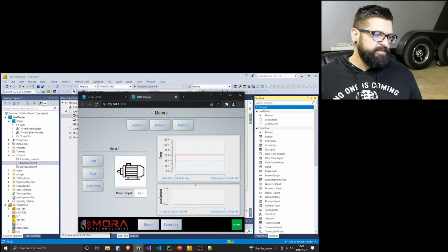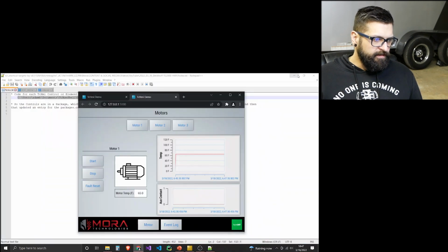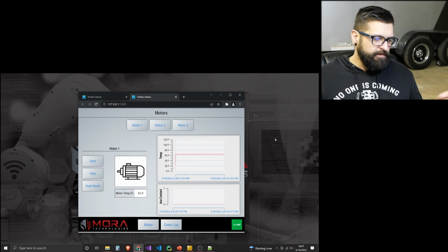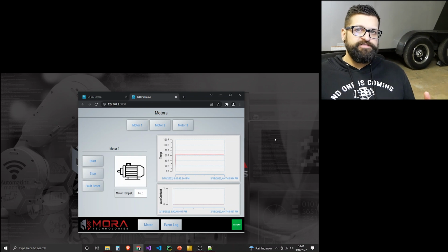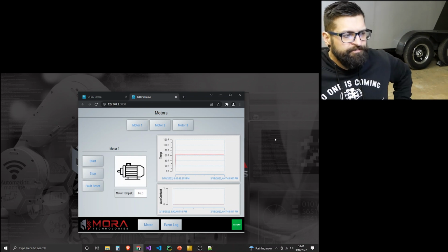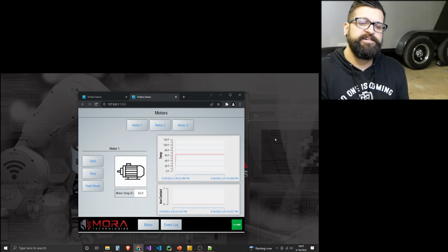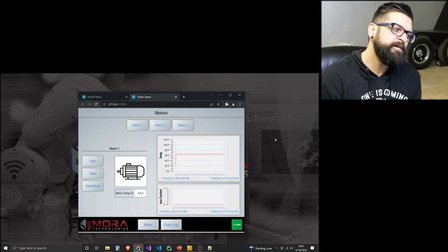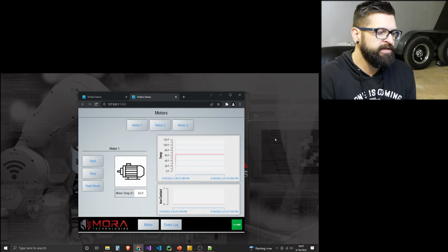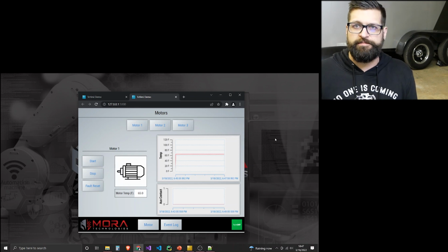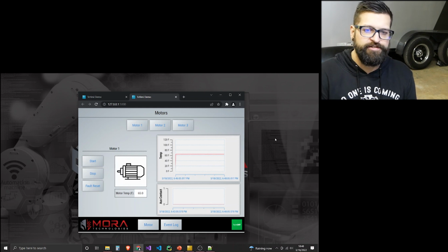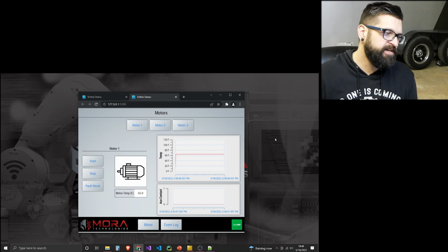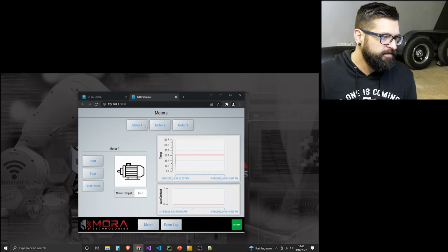What that came together with is this HMI right here. So let me drop all this out. For this HMI, I created a little program with 3 motors, function blocks. There's a TC event logger object in the PLC code. There's some messages, but largely it's just starting, stopping a motor, resetting the fault on a motor, and then I've written some simulation code to change the temperature when the motor is on. Temperature goes down when it's off. So we'll just see it in action right now.